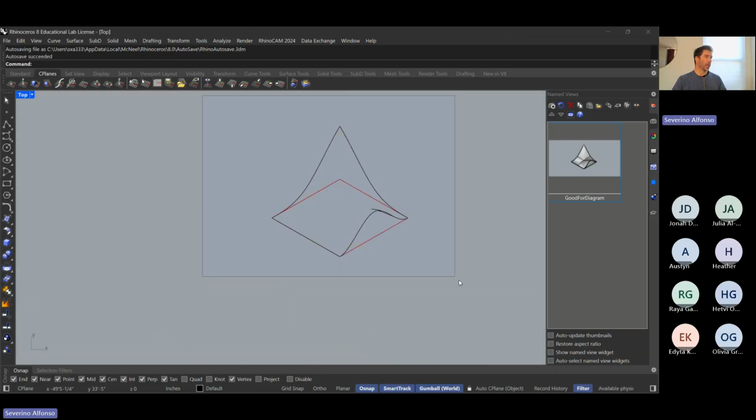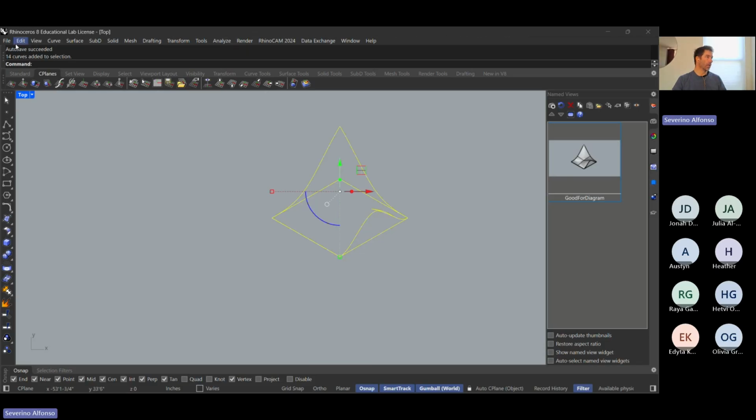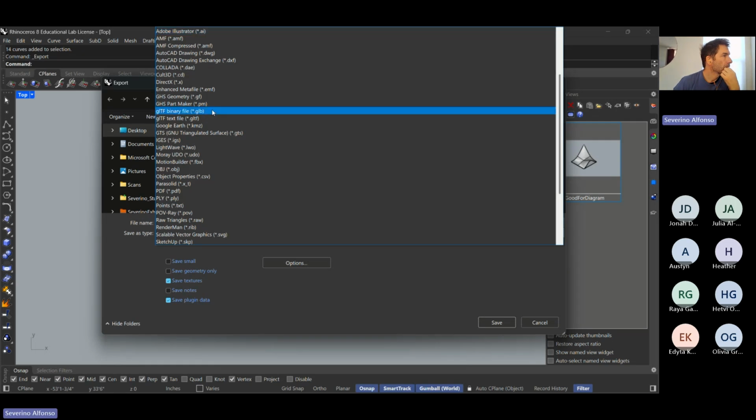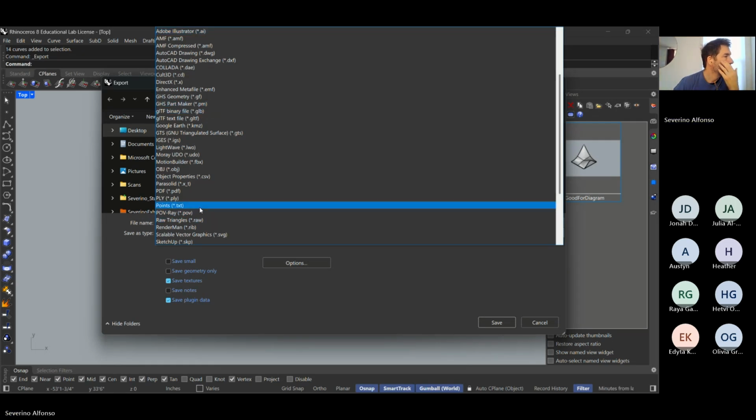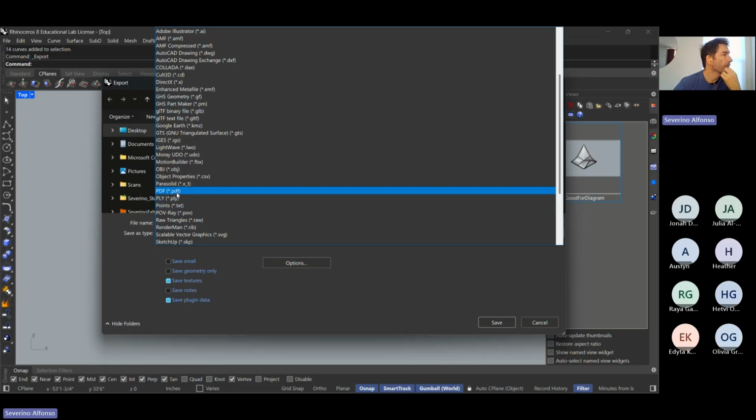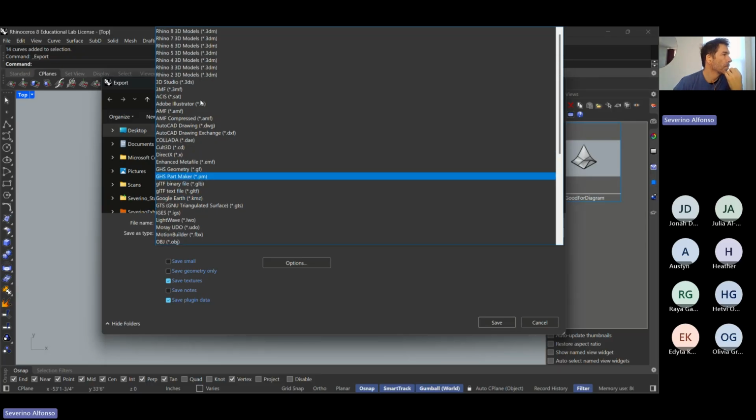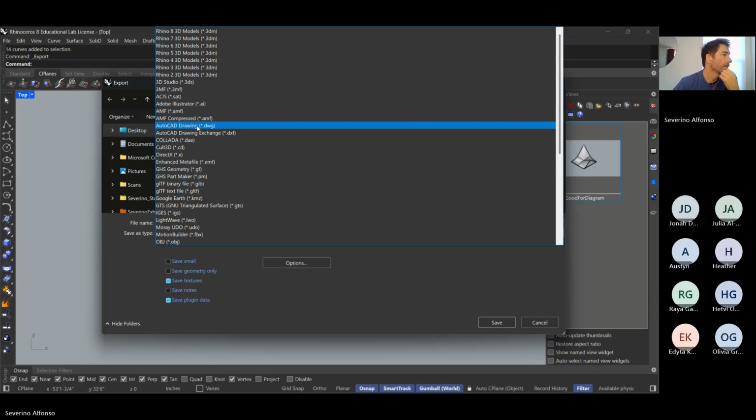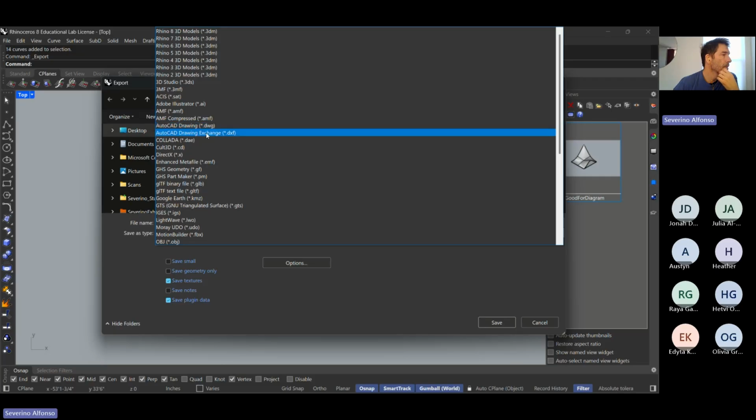So if I select from the top view this drawing and I say export selected, there are many options. The vector-based options are, well, you can do PDF even, but the most common ones are Illustrator, but also AutoCAD. And DWG is probably the better option, it is more for exchange, so you can send it to other software.